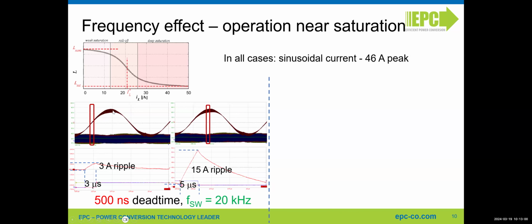But when we come to the 46 amps peak, you see clearly that the motor is entering this saturation area because the ripple is higher. If you do the di/dt, you see a 15 amps ripple on top of the peak of the current. This is responsible for the motor heating, and also vibration and loss of energy.